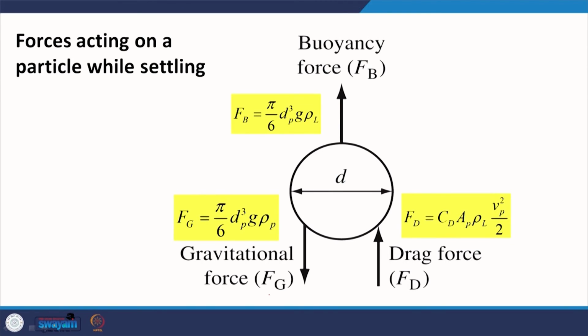So we have a particular velocity of settling, and we have the depth of our settling tank, and our particle should cover this vertical distance. Based on which aspect will it be governed? It will be governed by the settling velocity. Settling velocity, again, how is it coming into picture? Well, gravity is always our friend.